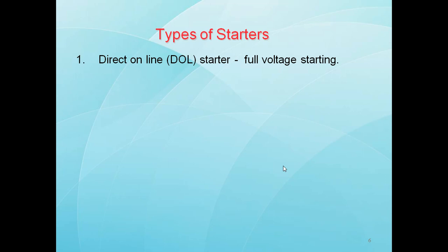First one is the DOL starter, that is direct online starter. In this case we apply full voltage at start. The next one is the auto transformer starter.